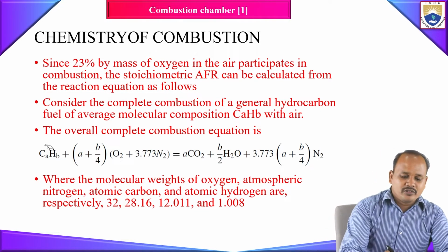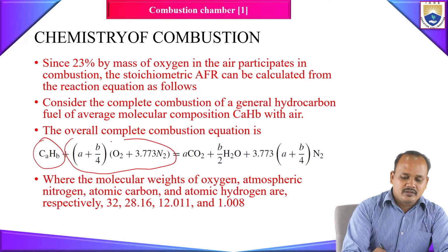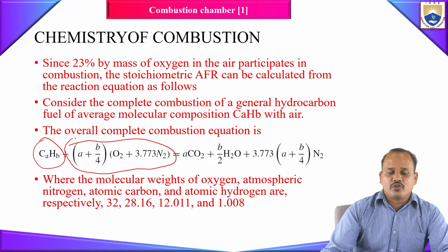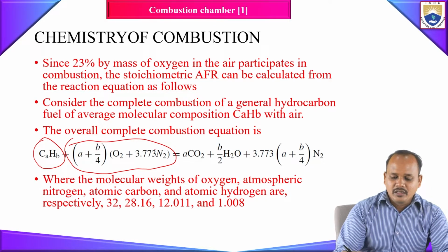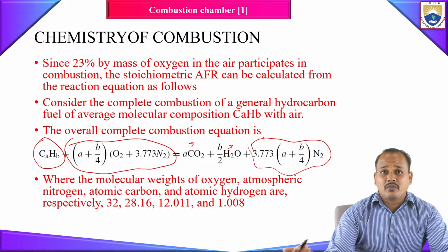Basically, this portion is your fuel, and this is your air. So when I have this much amount of air, complete combustion will occur. That is, a number of CO2 will be formed and b by 2 number of H2O will be formed, and the remaining will be nitrogen or nitrogen monoxides.